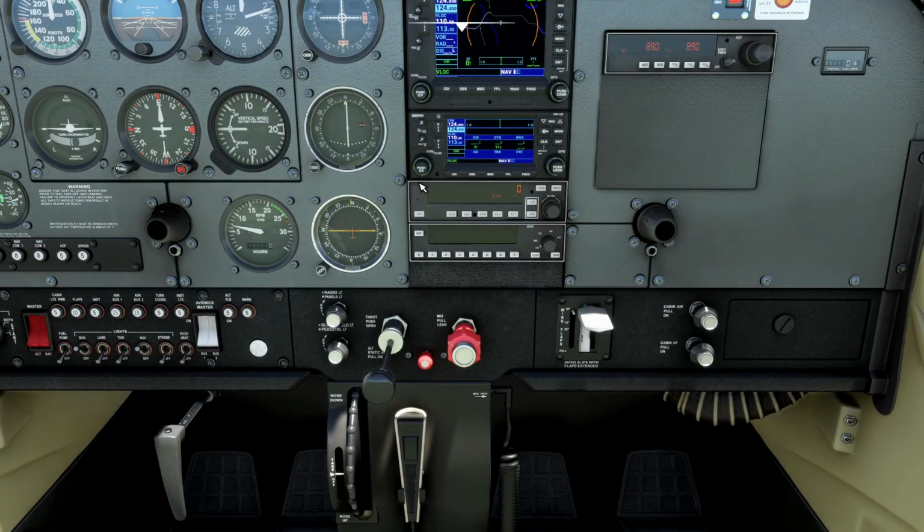There's not really any pre-flight test that's necessary for the autopilot in Flight Simulator. In the real airplane, you can turn on the autopilot and turn the heading bug, and then you can make sure the servos are working, because it will actually turn the control yoke on the ground, but it won't do that in Flight Simulator. In fact, I recommend against turning on the autopilot at all on the ground, because if you do that, it will move your trim wheel and put you out of trim for takeoff, so I don't recommend that.